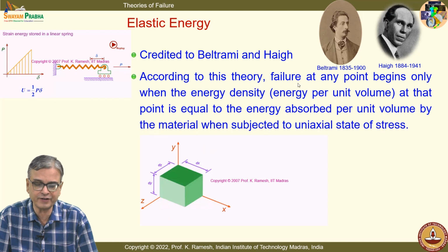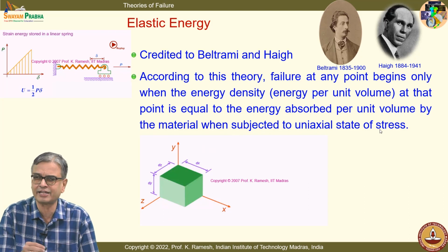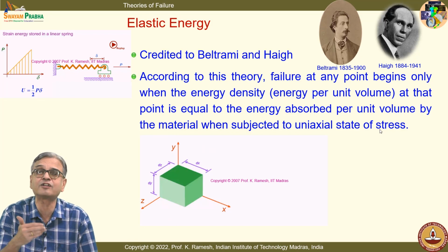According to this theory, failure at any point begins only when the energy density at that point is equal to the energy absorbed per unit volume by the material when subjected to a uniaxial state of stress. These are all like, when you are proposing a theory, you feel instead of concentrating on other quantities, let me concentrate on the energy. That is how they proposed it.